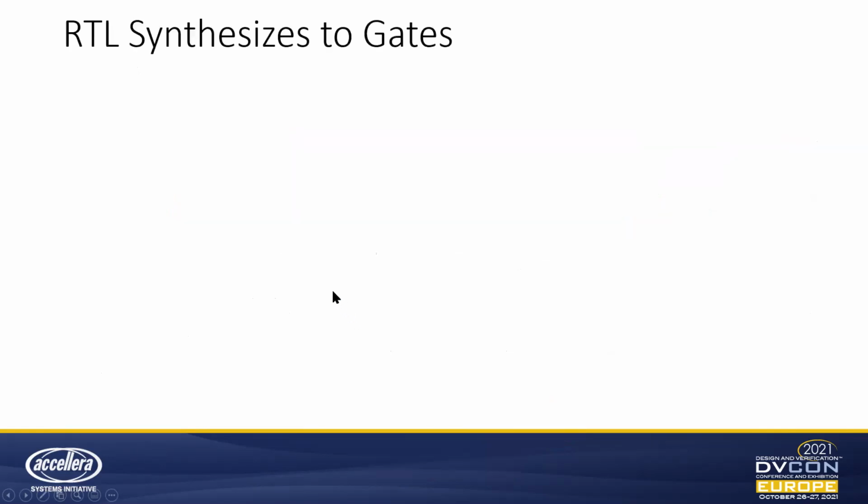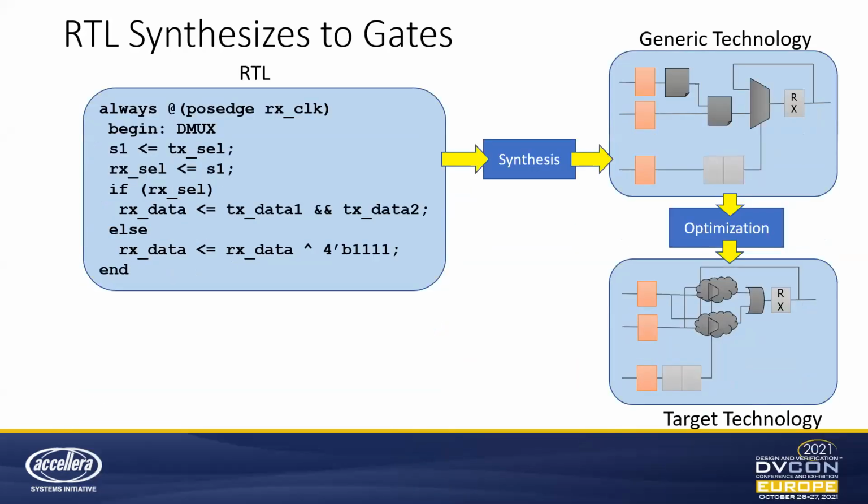The next slide tells how the changes introduced in the netlist during synthesis can lead to potential issues. Changes introduced in the netlist during synthesis, such as timing optimization of synchronization logic and insertion of design for test logic, may cause incorrect behavior in CDC synchronizers, or introduce new CDC paths, or can break valid CDC paths.